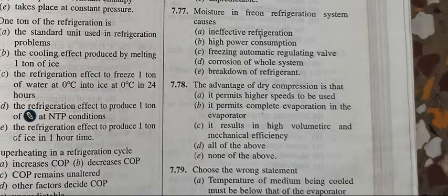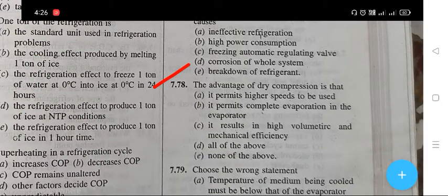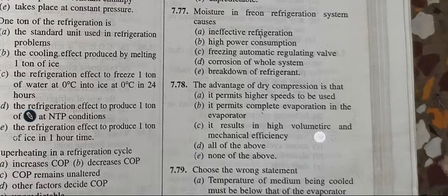Next question is the advantage of dry compression is that. Right answer is D, all of the above, that is it permits higher speeds to be used and it permits complete evaporation in the evaporator and it results in high volumetric and mechanical efficiency.